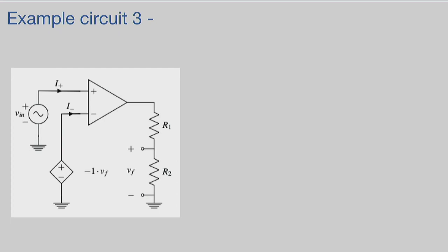Let's see. Confident that it is? Well, we have to take a look. Where is our V out? We would measure V out here, right? It's missing here in this circuit. We would measure V out here. We have V feedback. So if I wiggle V out, which is here, that means I am increasing the output. If I increase the output, what happens to VF, which is right here?